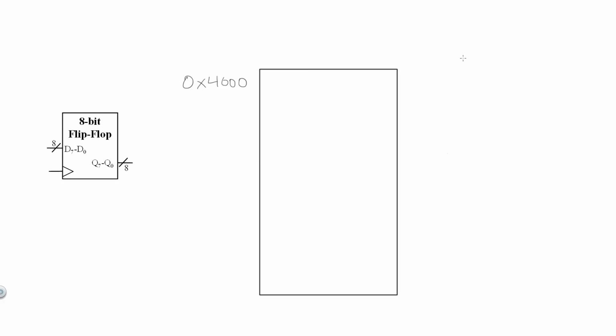To answer this question, we must first understand the difference between full and partial address decoding. Full address decoding is when all of the address bits that are not connected to the external device are used for address decoding. An example of this would be the SRAM we connected in the previous example. We used the lower 15 address lines to connect to the SRAM, and all of the higher address lines were used in decoding of the chip select. Thus, the SRAM was fully address decoded.